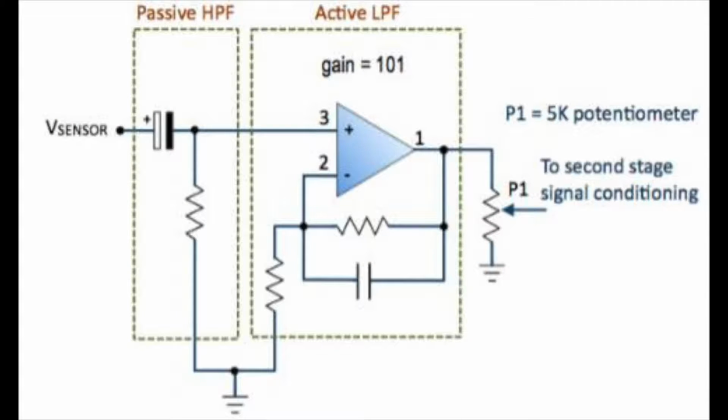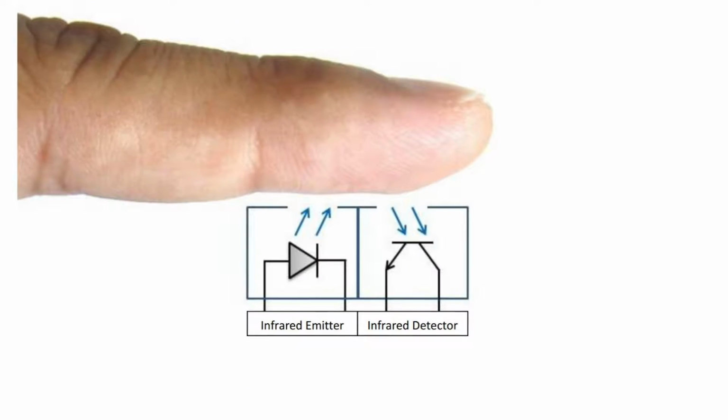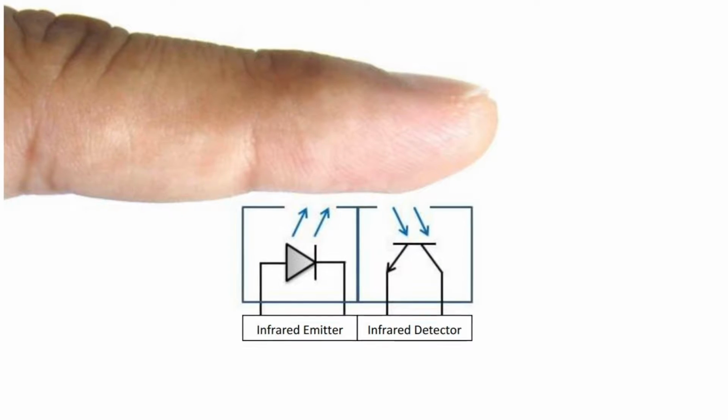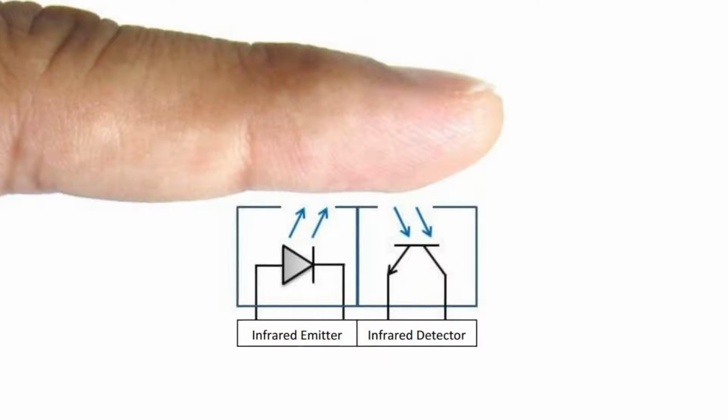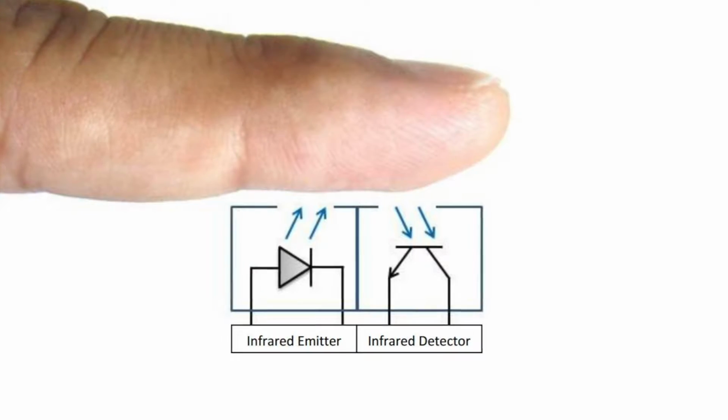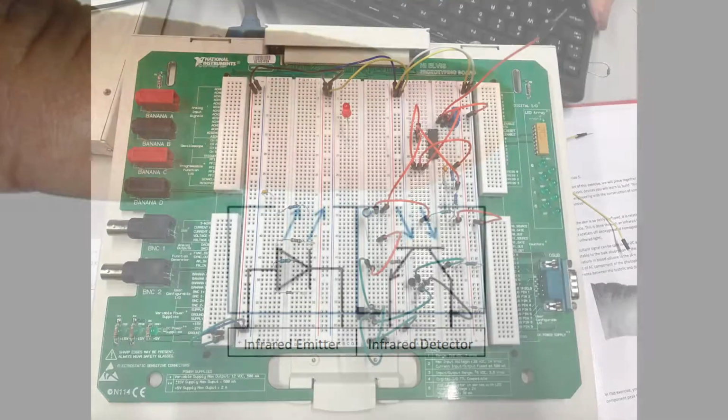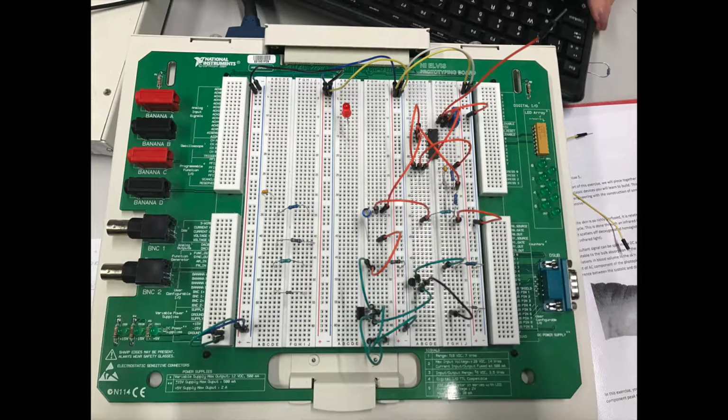In part 1, in exercise 4, we put together a photoplethysmographer using an infrared light and several classic devices. A photoplethysmographer is not only clinically relevant, but also very inexpensive. This is done through an infrared light emitter and an infrared detector that picks up the light that scatters off the oxygenated hemoglobin in nearby blood vessels. The circuit will filter this infrared signal and employs the AC component peak to light a LED, which will therein serve as an indicator for the heartbeat.